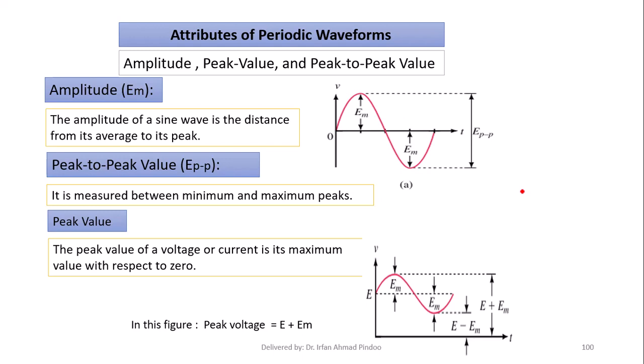What is the amplitude? Now amplitude is nothing but, if you see the diagram, it is the maximum value. Okay, if you see in this diagram, we have a value here which is the maximum value. Similarly, we have a maximum value in the positive half, and a maximum value in the negative half. So both are called amplitudes, and the difference between these 2 points is called the peak to peak value. Amplitude is also referred to as the peak value.